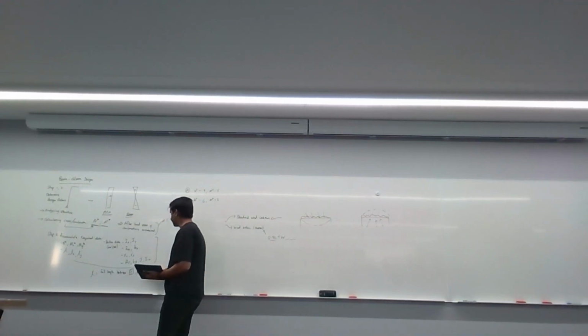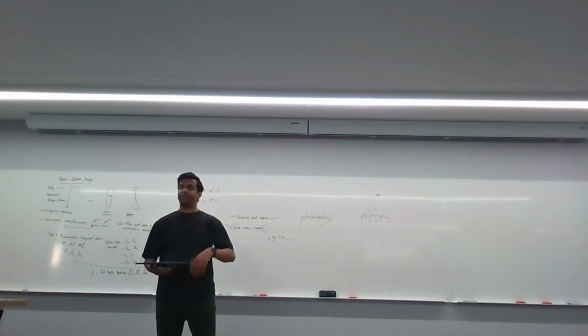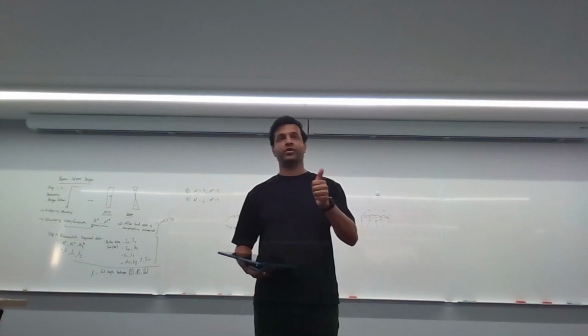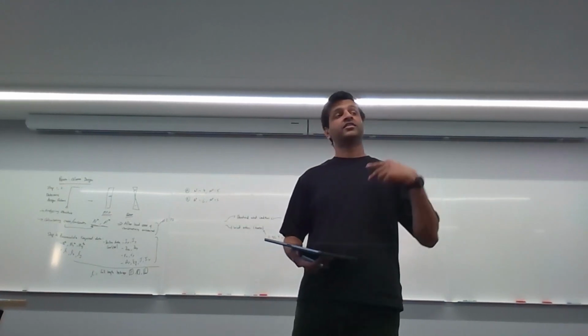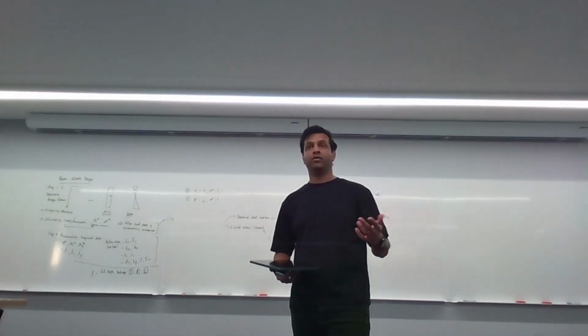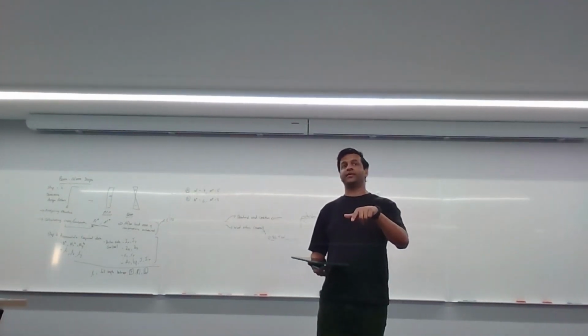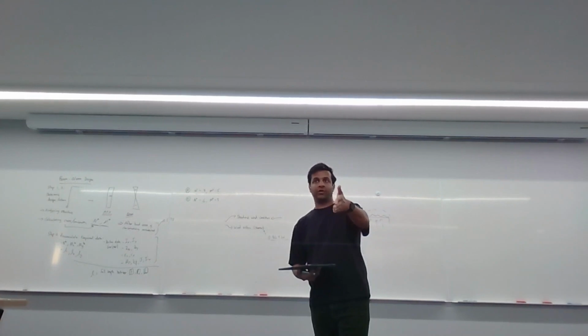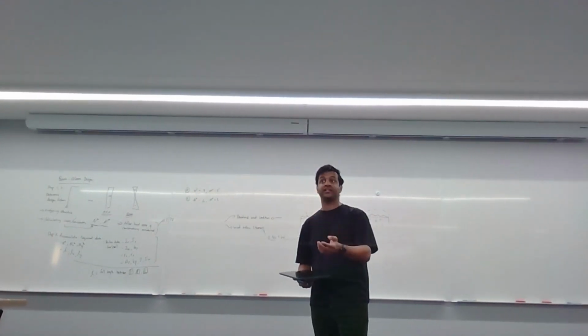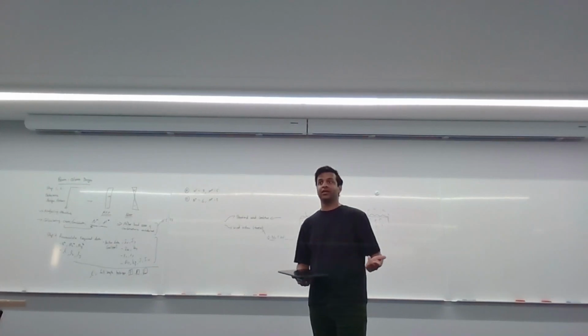Okay. Now, a very important part of this topic and beam bending topic is to understand what the differences are between your full restraint, partial restraint, and lateral restraint. Because sometimes the questions can say what they are, and sometimes they won't. If a question doesn't tell you whether this is a full restraint or a partial restraint or a lateral restraint, but it just shows you what the connection looks like, it's up to you to actually decide what it is based on it.